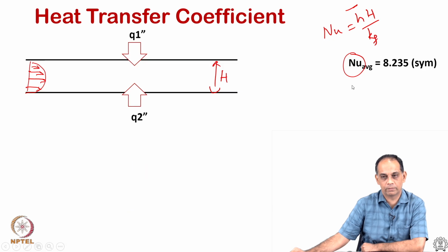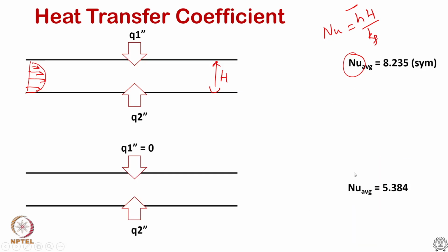If you derive the solution, it is not exactly half, it is actually a little more than half of this Nusselt number. Why is that? It is because of the convective heat transfer that happens, and the boundary layer growth is going to be very different in this case. The thermal boundary layer will grow and actually make contact with the top wall. Indeed, if this top wall is conducting, the wall will get heated by this thermal boundary layer as heat is picked up by the flowing medium.